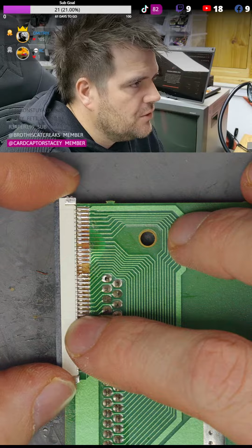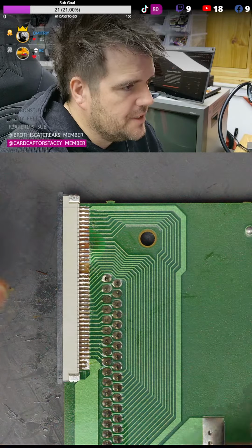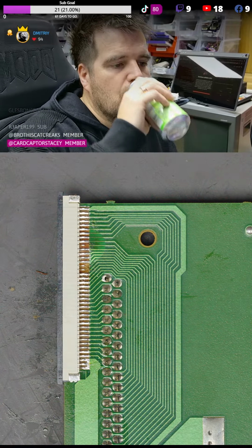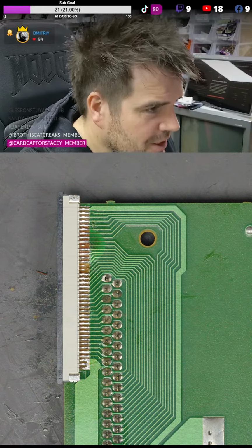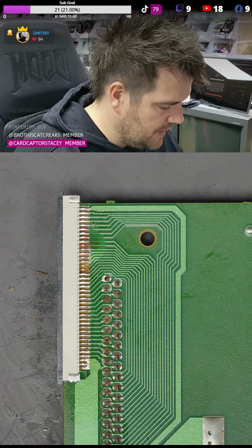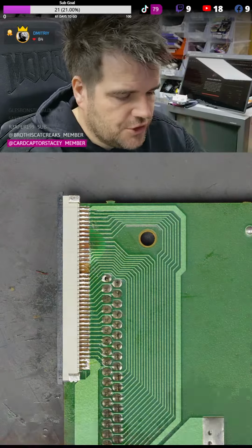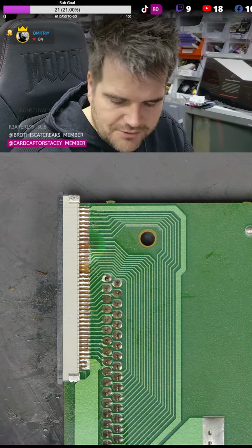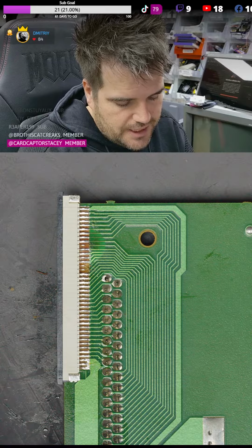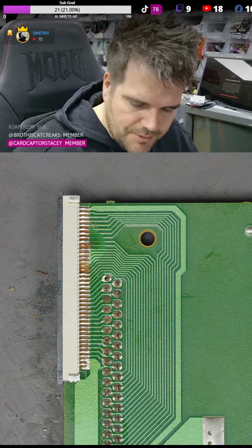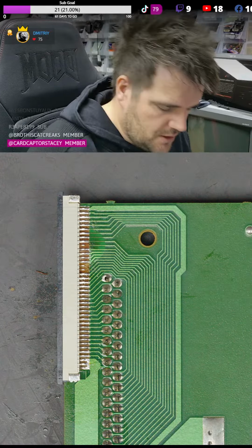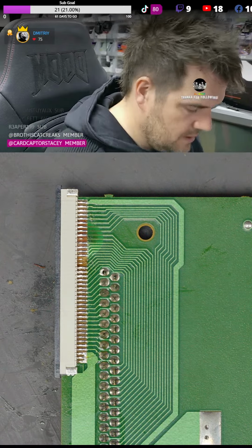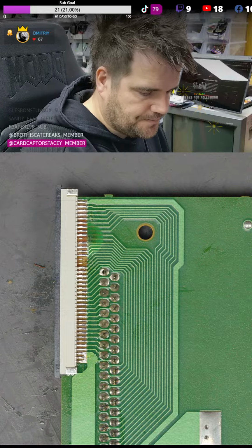Yeah, we can use low melt solder as well. I've got tons. I'd normally hot air them connectors off. I was just showing the technique with the soldering iron, but because I showed the hot air in the last stream, I thought I'd just show the soldering iron way at the start to give you an idea. I've got massive sticks of low melt solder, again from a factory where I get most of my stuff from. So huge bars, but I just never use it. It's not something I rarely need or use.